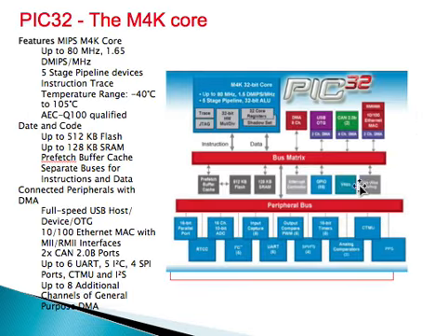Normally the PIC32 is a Microchip 32-bit microcontroller. It's on top of the range. As you know, microprocessors can be 8 bits, 16 bits, or 32 bits, and they are normally very fast. This one, for example, runs up to 80 megahertz. However, you only need a clock of about 8 megahertz, and it has what they call a phase lock loop, which multiplies and increases the speed.